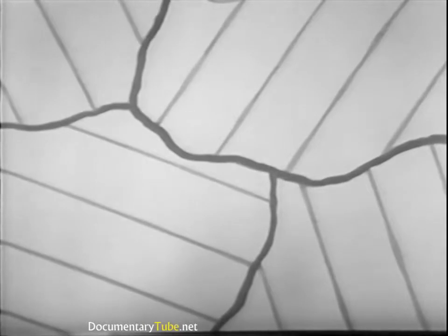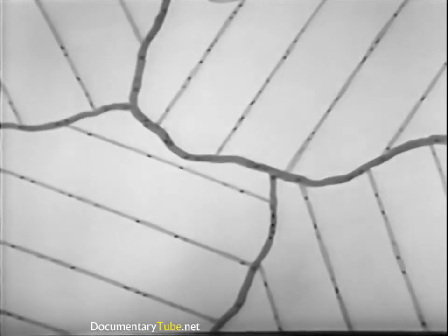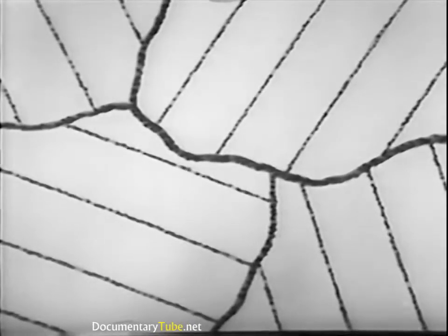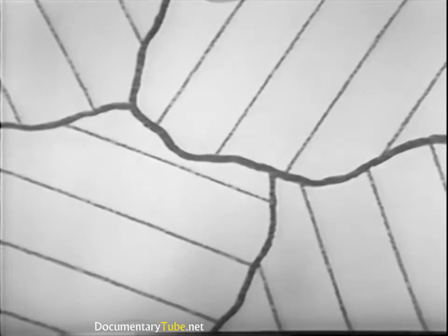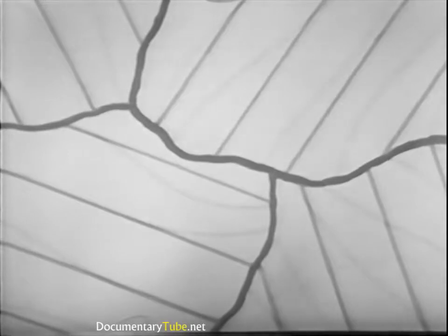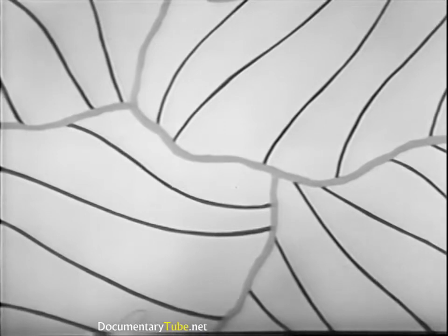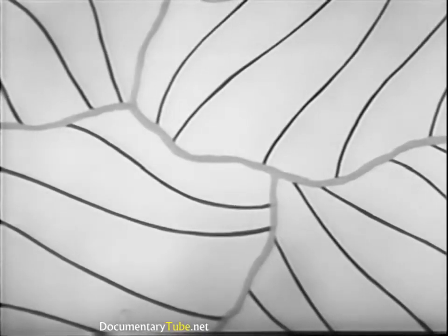Another theory, the fragmentation theory, states that during plastic deformation, minute crystal fragments break off and fall along the slip planes and grain boundaries. These fragments interfere mechanically with further slip by increasing the friction between crystal blocks and between grains. A third explanation, the lattice distortion theory, assumes that the crystal planes become bent and twisted during plastic deformation. The distortion of these planes and also of the lattice structure at the grain boundaries increases the resistance to further slip.